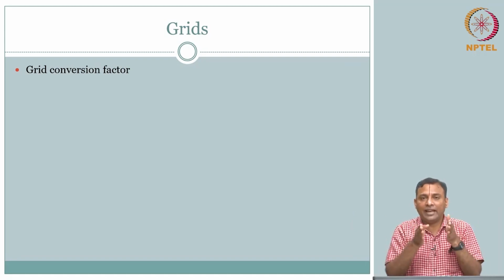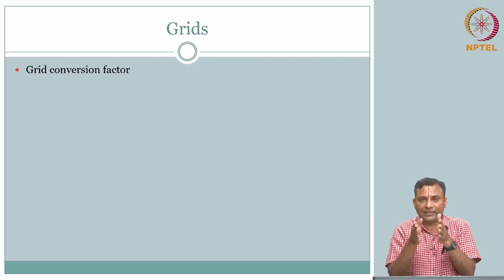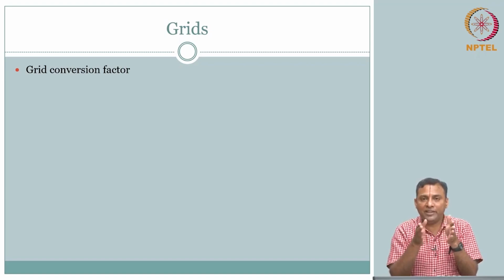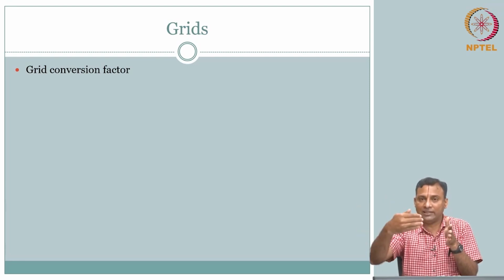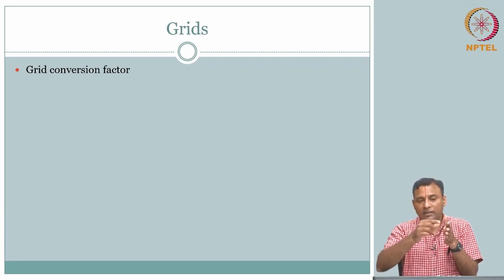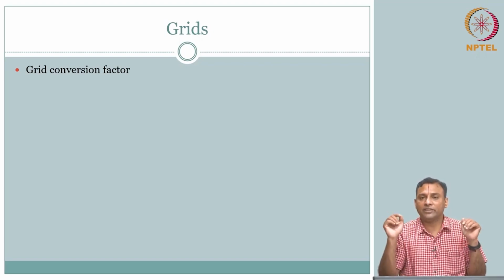So, in some sense you are getting the signal only through the transparent window that is sandwiched between the gap between the leads. Not only does the height of the lead control which angle is absorbed, but whatever is coming and hitting the lead itself is also lost. Your signal is also lost wherever the grid is physically placed.